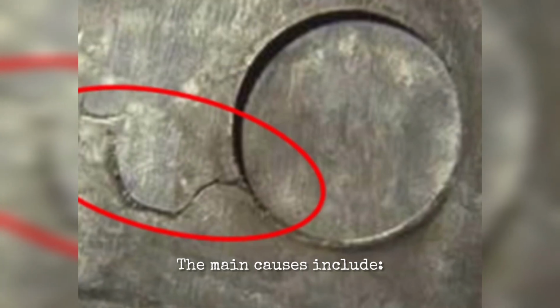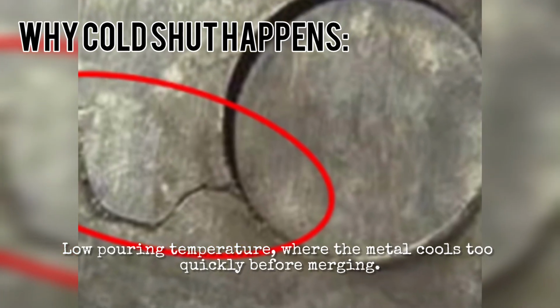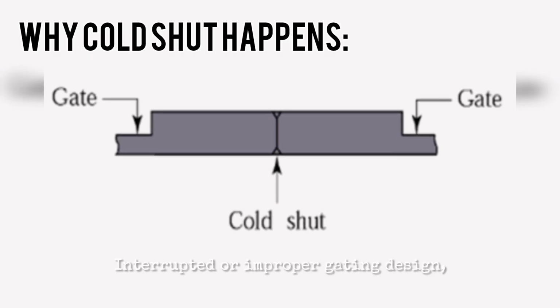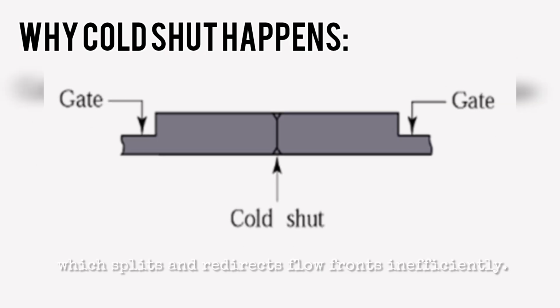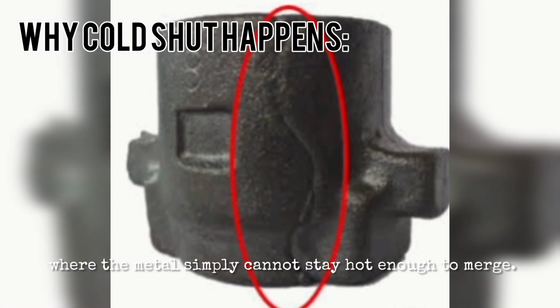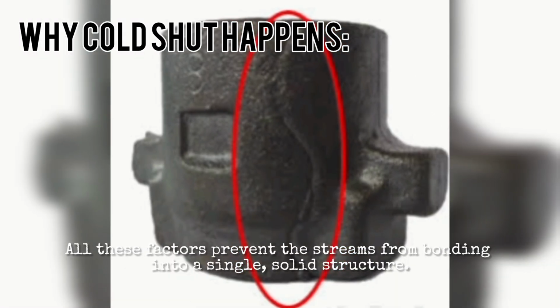The main causes include low pouring temperature, where the metal cools too quickly before merging, poor fluidity of the molten alloy, making it harder for the metal to flow evenly, interrupted or improper gating design, which splits and redirects flow fronts inefficiently, and sometimes long and thin sections in the mold, where the metal simply cannot stay hot enough to merge. All these factors prevent the streams from bonding into a single, solid structure.